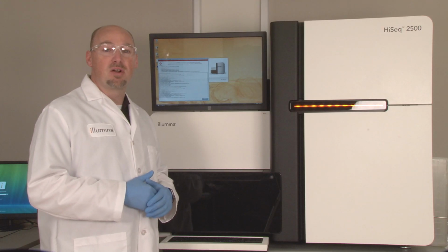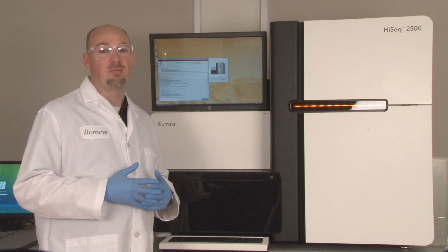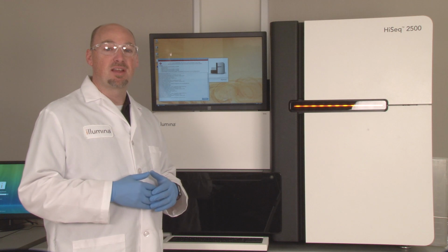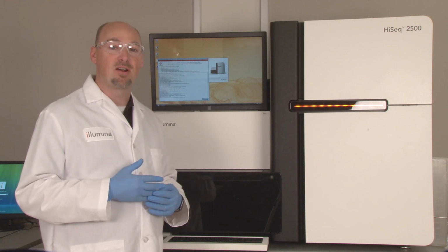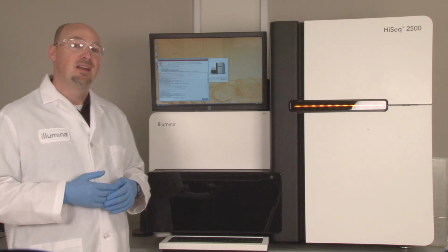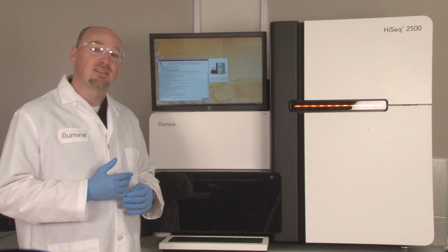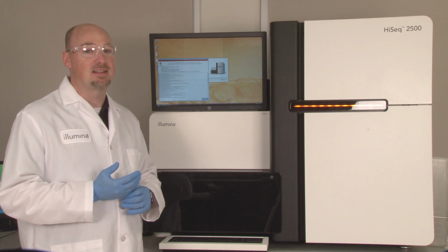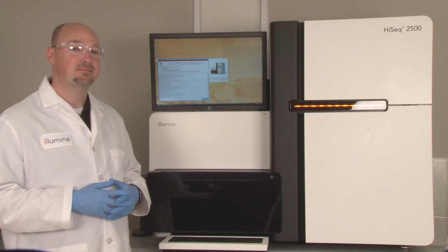When communication ports are closed improperly by the software, new communication can be claimed by the incorrect port number. After a communication port is claimed, it reconnects in the same order with a simple restart of the computer. An incorrectly connected communication port prevents the HiSeq control software from communicating with the subsystem normally allotted to that port, which would cause an initialization failure.